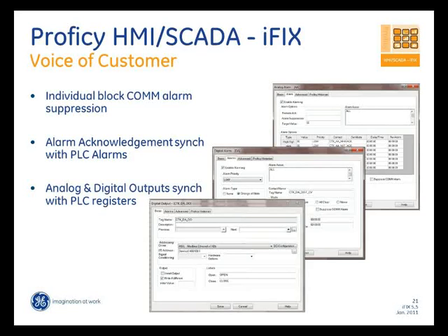So that has led to a change in behavior of our analog and our digital output. There is a checkbox that we have introduced in analog and digital output that prevents the AO and the DO from writing out in case the block is reset, which means if you reload the database or iFIX starts over, you can prevent the analog and digital outputs from writing out to the PLC and force a read first to make sure that they are synchronized. So that's something that we've added to AOs and DOs.